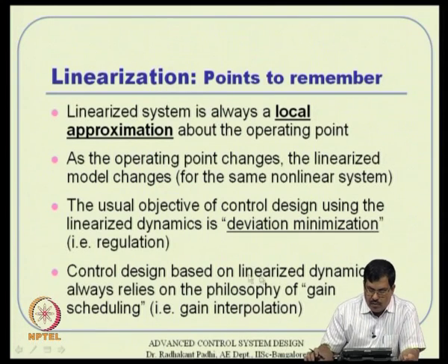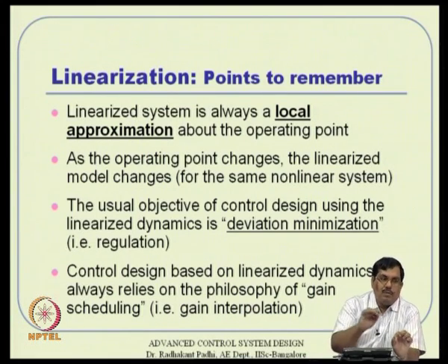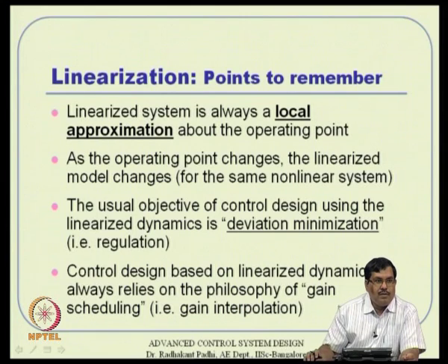because these linear control systems are based on linearized system dynamics which keep on changing with time, anywhere you use linearized system dynamics to design a control system, you must also follow the philosophy of gain scheduling. Because the linear system you get for one operating point is different from that at a different operating point. So, if you want a control system which is valid all over, then you have to bring in the concept of gain interpolation, or what is called gain scheduling. And then the interpolation variables are an issue themselves: what variables to select for interpolation.